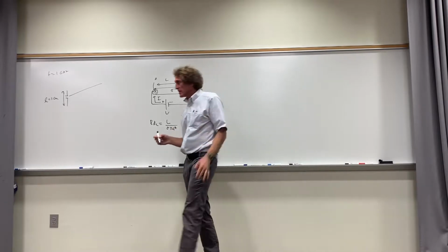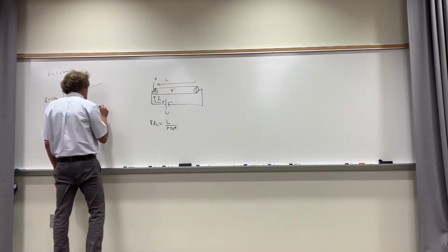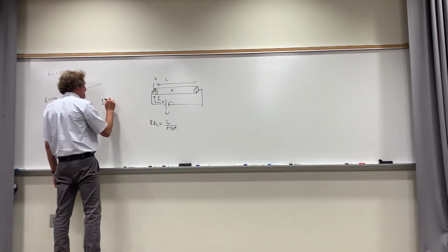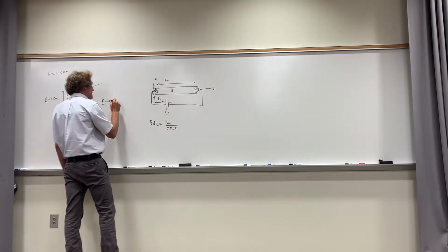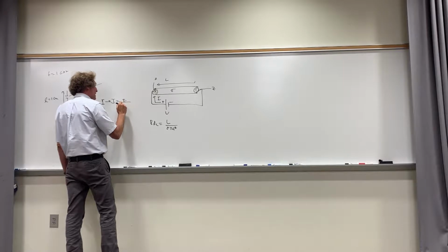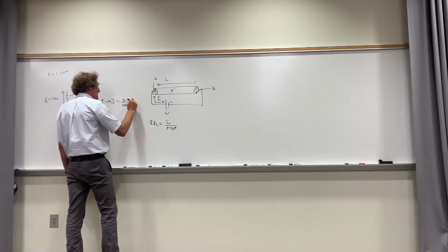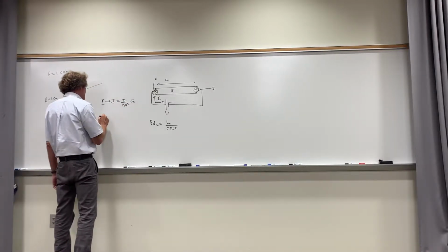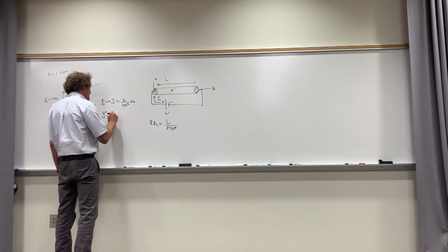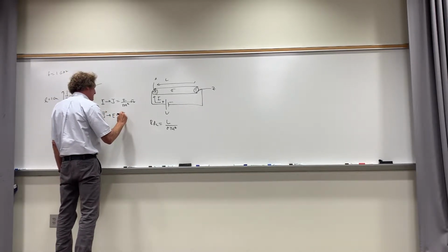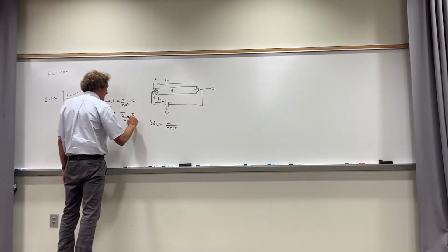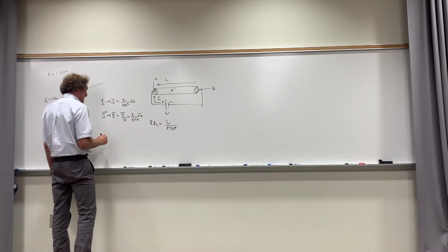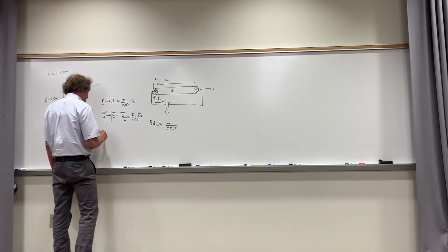The classic way, just to recap, normally you assume I, and then you get J, call that the Z direction, and J would be equal to simply I over pi A squared a_z. After you have J, then you get E, and E would be equal to J divided by sigma, and that would be equal to I over pi A squared sigma a_z. And then once you had E, you would find the voltage.